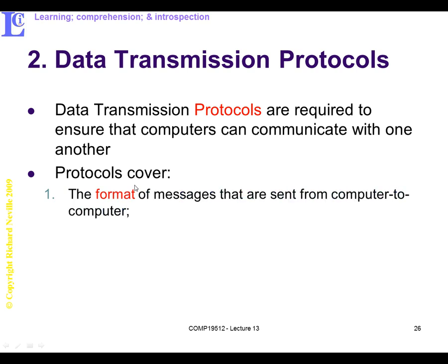First thing is how the information is put together, what the message looks like. If it's got a start bit, if you remember, we've just seen on our serial sequence of sending digital bits, it had a start bit where the signal changed from a nominal value to another value to tell the receiver that after this low, here comes the signal, if you're running at the right clock rate, that is. So we need to know in these protocols what the format of the message is.